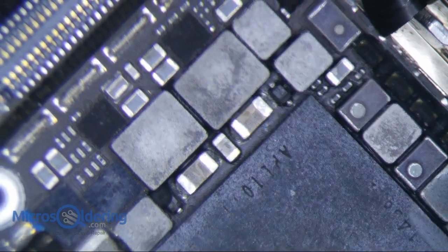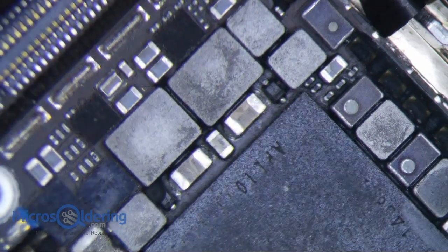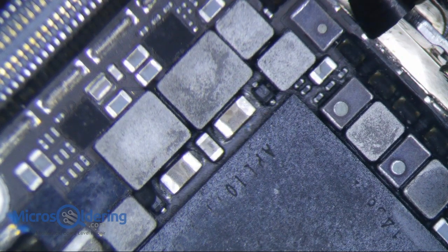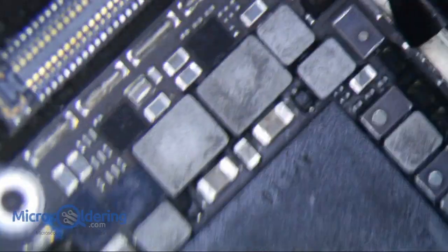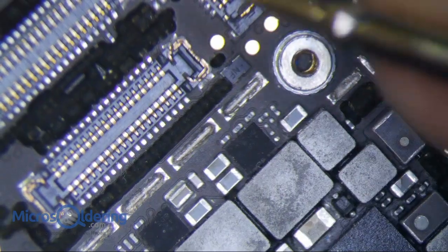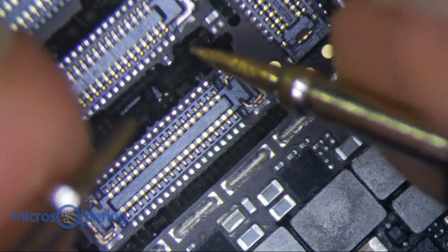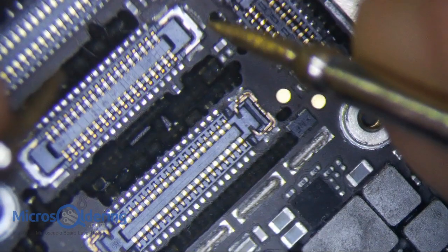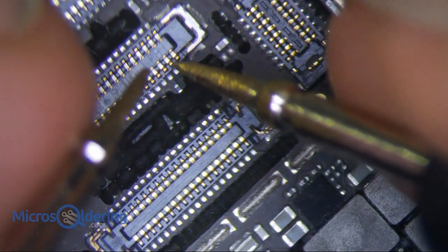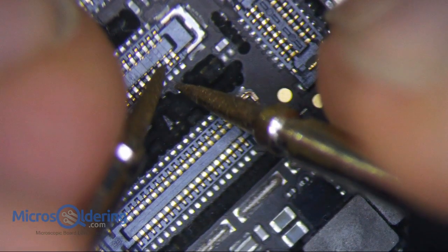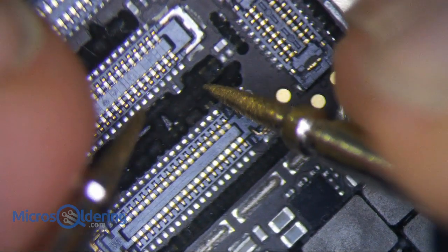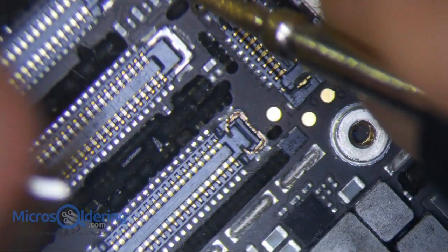Okay, let's just disconnect it, and let's just go through our checks real quick. So I'm going to change the multimeter to continuity mode, diode mode. Alright, and let's measure some of the filters first. Okay, so I don't even remember which filter it was now. I think it was.